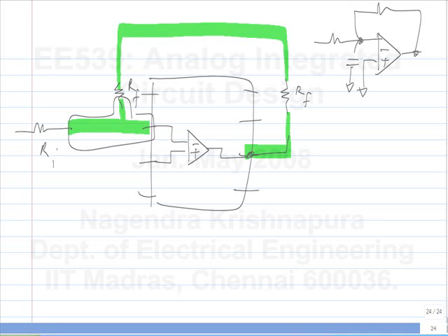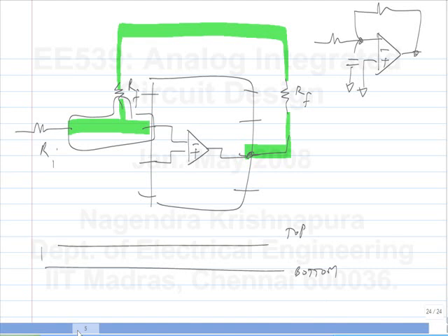And in very high speed circuits, what is done is you have multiple layers of copper. Let's say just take two layers. This is the top and this is the bottom. Okay, so you usually have a solid ground plane, that is the bottom is completely an unbroken copper layer, so that you get a good ground plane.